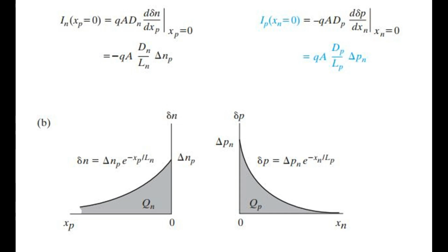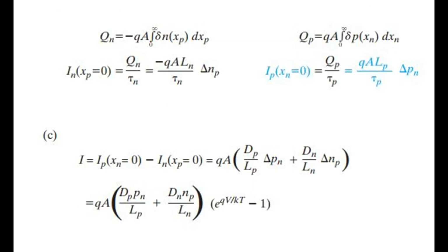One implication of Eq. 5.36 is that the total current at the junction is dominated by injection of carriers from the more heavily doped side into the side with lesser doping. For example, if the P material is very heavily doped and the N region is lightly doped, the minority carrier concentration on the P side, np, is negligible compared with the minority carrier concentration on the N side, pn. Thus the diode equation can be approximated by injection of holes only, as in Eq. 5.33.